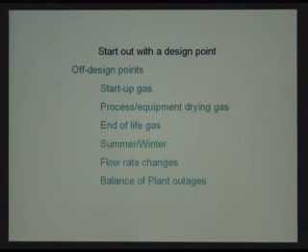For example, if the mole weight is going to be dropping through the life of the plant, and you only need 4 impellers to meet your current process conditions, but at the end of life you may need 5 or 6, the compressor vendor can actually make the casing longer and put blank sections in, which you will then populate with additional wheels as your mole weight drops. So it makes it relatively inexpensive to change the equipment to match the future process requirements rather than having to buy a whole new compressor.